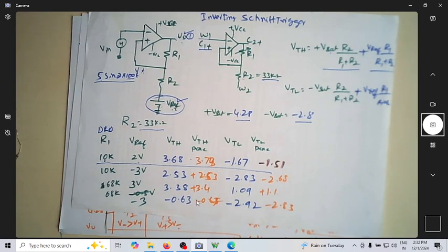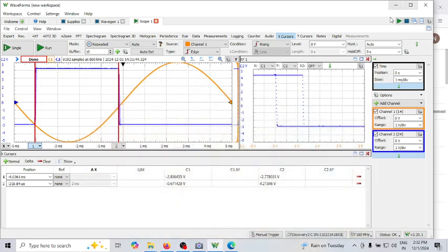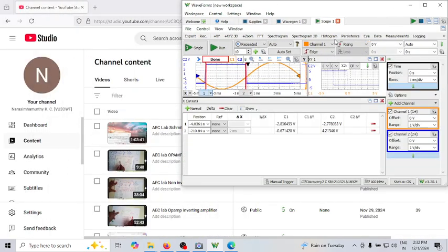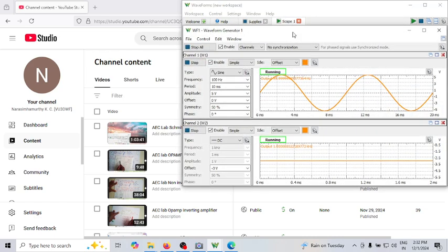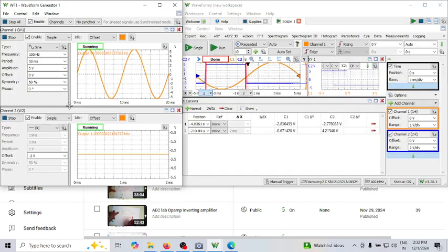So now here both VTH and VTL are negative. So we can see in the above two cases, one is positive, one is negative, and in these cases both the voltages are positive, both threshold voltages are negative. It's possible only with, you can see now it has become less than 0. So let me just run here and then show you how it will happen. So let me just take this out and let me vary this reference voltage and then see how the hysteresis moves.